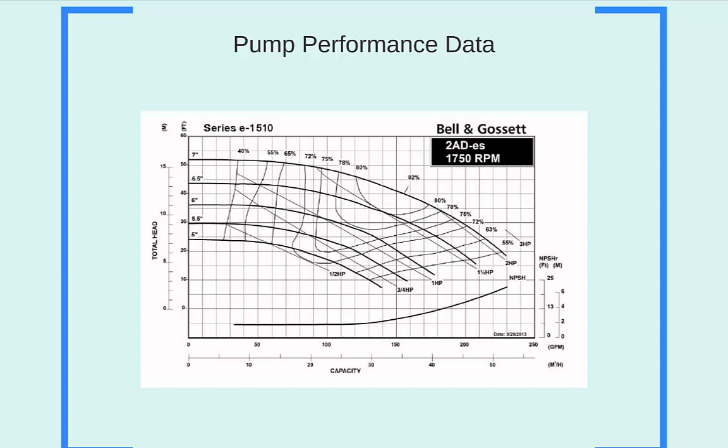There are a lot of lines here, but let's focus in on those that start horizontally on the left side of the plot and start to slope downwards as you follow them to the right. These curves are termed pump curves. There are several of them for different impeller size options. Let's just focus in on the top one for a 7-inch impeller.